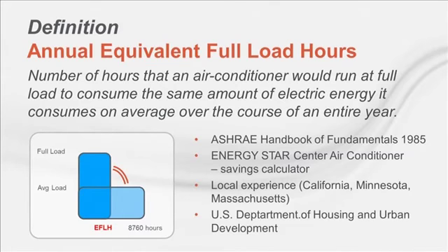The idea for using the equivalent full load hours is to simplify energy saving calculations. For example, Energy Star develops an Excel-based calculator to calculate the annual operating savings using equivalent full load hours. The equivalent full load hours in this case is varied by the states. Minnesota and other states also develop equivalent full load hours that vary by building types. Mick will show an example from ASHRAE handbook later on.